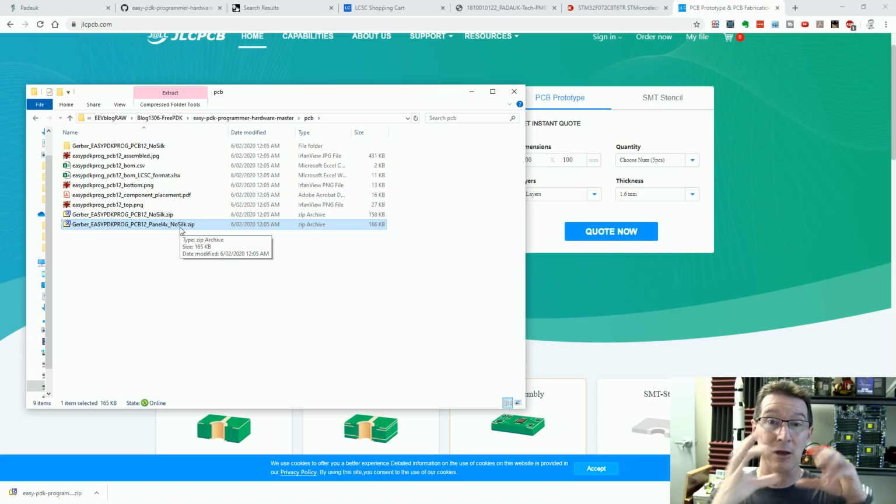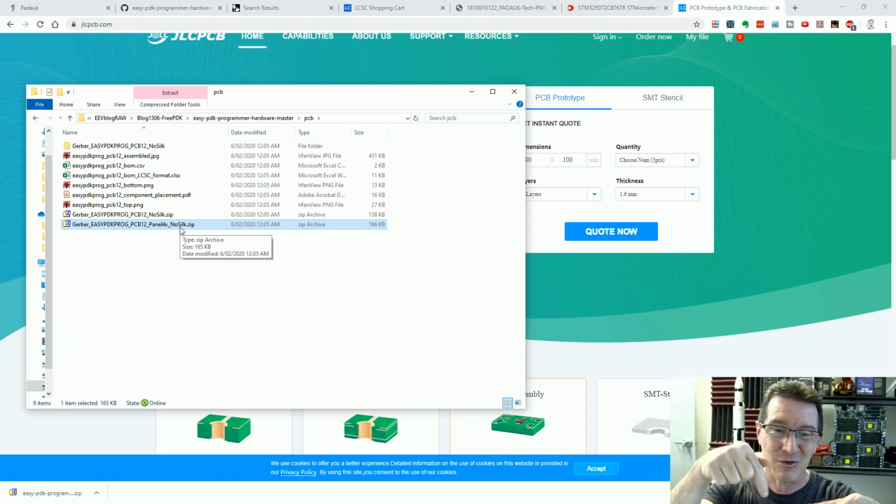You can't just say, okay, I want my board, but it's only this big, but I also want four V-scoring grooves in there so I can snap them off. It doesn't work like that, because V-scoring has to be done on an entire panel basis. They can't just go in selectively and V-score your individual board. It has to go through.